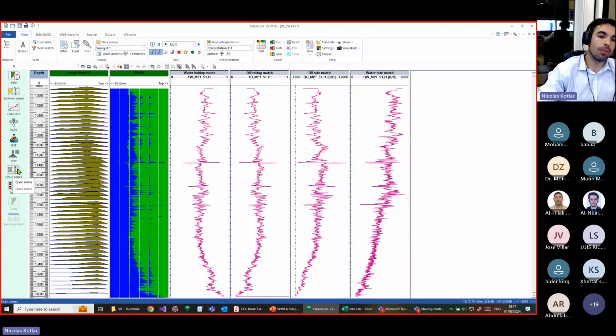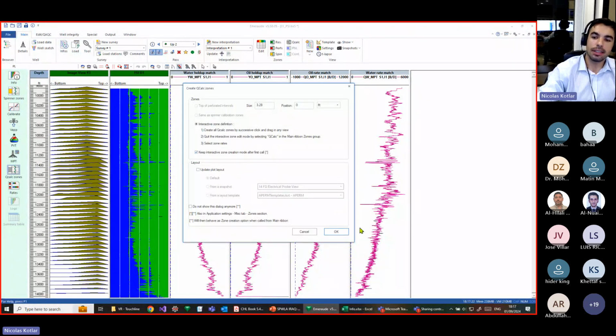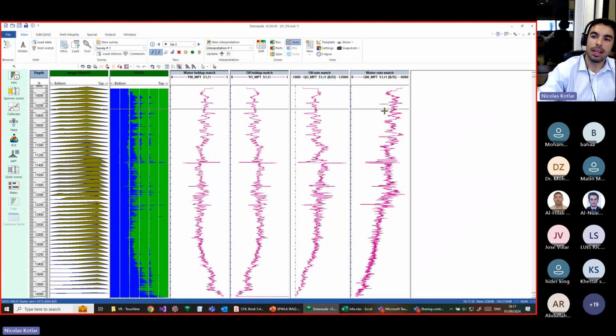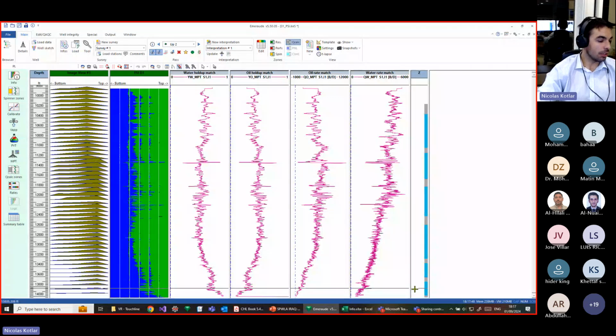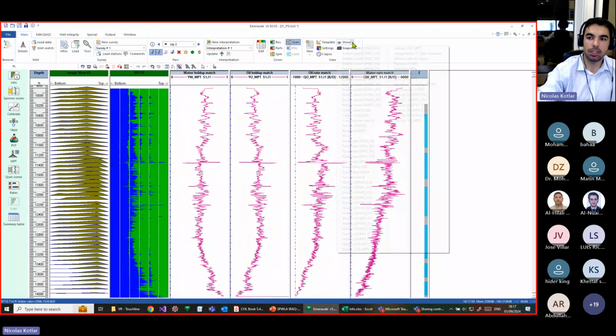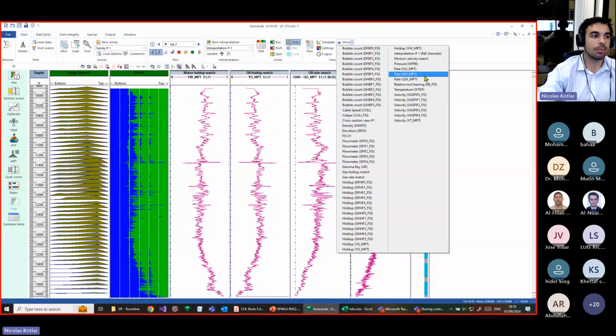For this, I'm going to set myself here QCalc zones, and then an interactive definition. In gray here, I'm setting rate calculation zones, and in between these rate calculation zones is from where the rates can actually change. In blue, these are the so-called inflow zones. For the inflow zones here, I'm being arbitrary based on what I see, that there are changes in rate. In your case, you can use geological information as well. Another good source for inflow zone definition is the temperature, which I didn't even show you. In this case, how the temperature looks like.